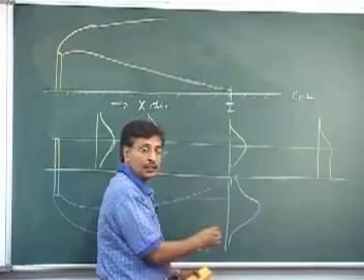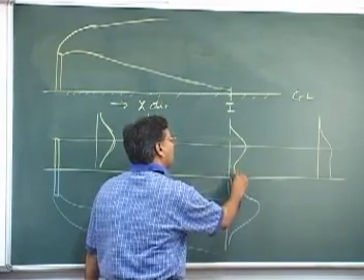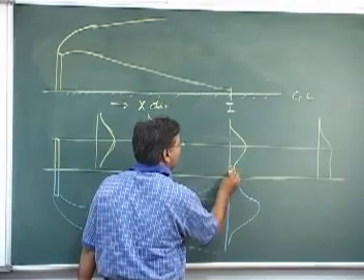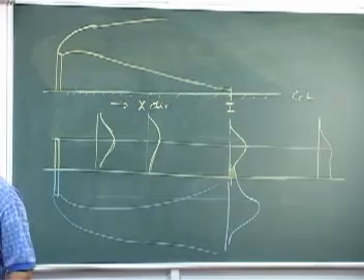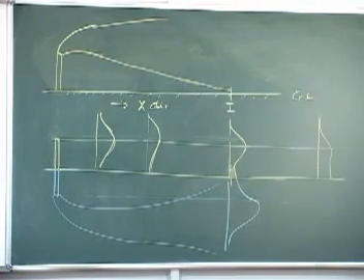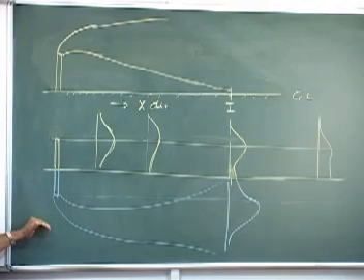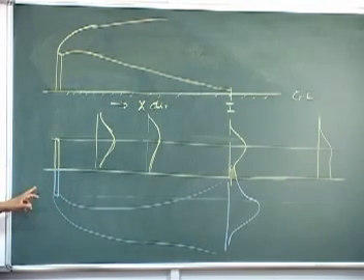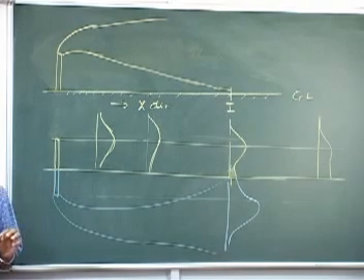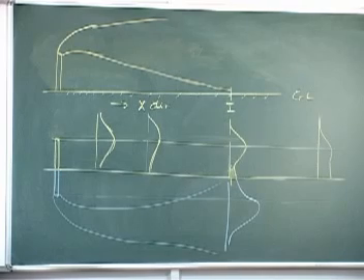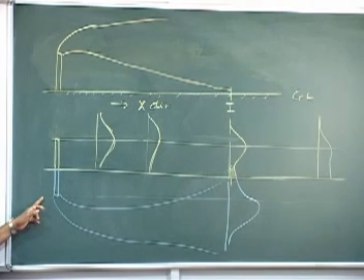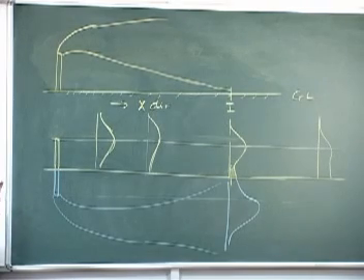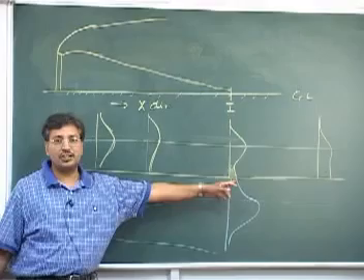So it is not reducing asymptotically, but reducing like this. So you might have a slight addition of concentration in this range, and I must account for this change. I must account for the reflection of my plume, and I am accounting for that as if this is an inverted source. I can write the same equation for this particular source. Earlier we put z equals z minus h for this source. I can write the equation for this source by putting z equals z plus h, and I can add those two equations and get the concentration here, right.